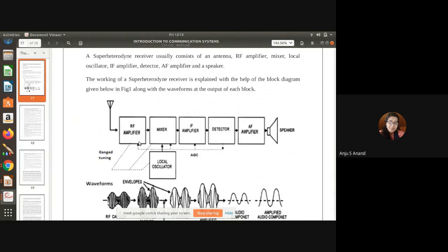What was the property of a superheterodyne receiver? This one part is called mixing. The mixer generates an intermediate frequency, that is, a decreased frequency spectrum is created by combining our incoming radio signal along with a locally generated signal, generating the sum and difference of the two signals.